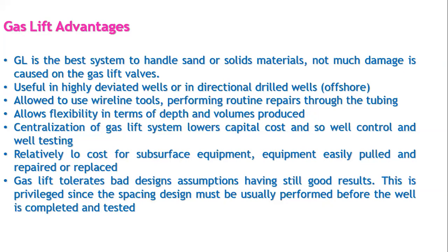Another positive thing about this system is that anytime we can run wireline tools to perform some repairs through the tubing, which is not something we can do with any pump in the well. Unless, in the case of the ESP, we have a Y-tool, but in other conditions we cannot. We have to pull everything just to do, for instance, logging.